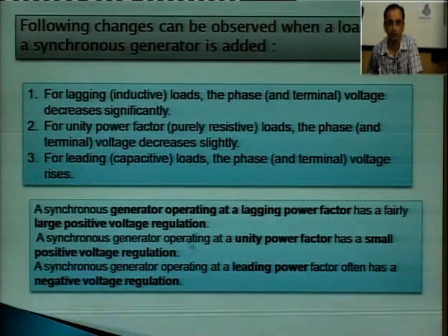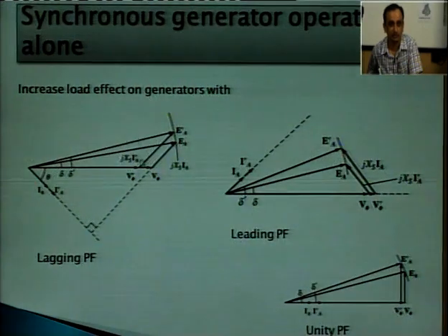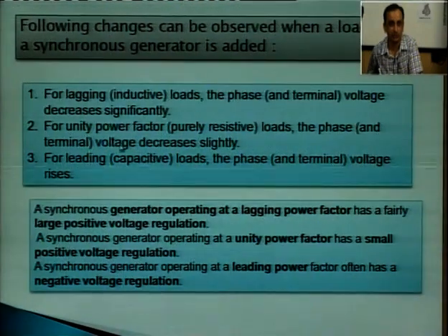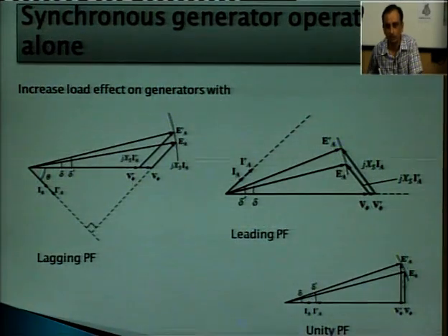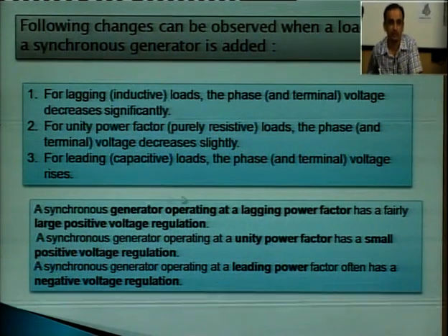We can conclude from this figure that for lagging load, the phase voltage decreases significantly. For unity power factor the voltage decreases only slightly, and for leading, this change is slightly larger.